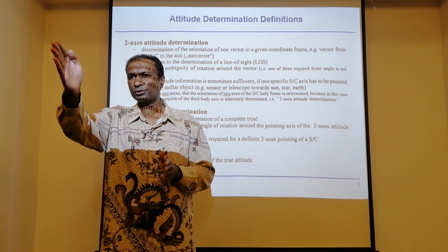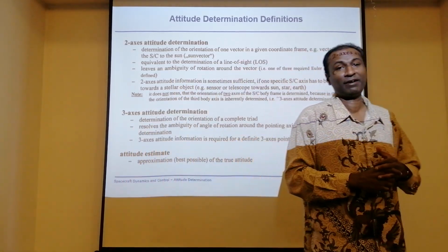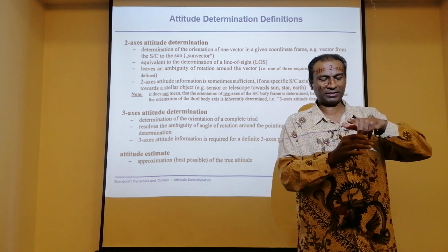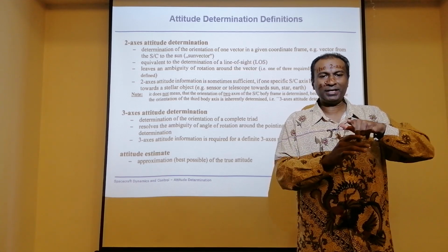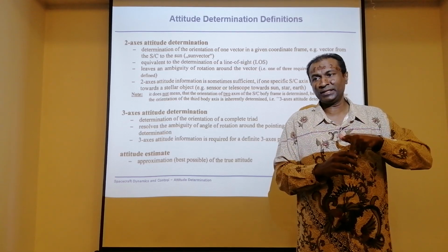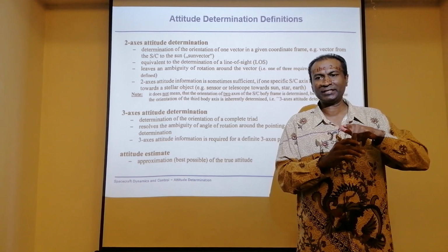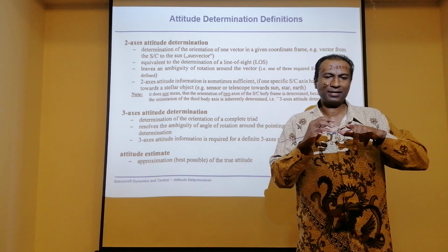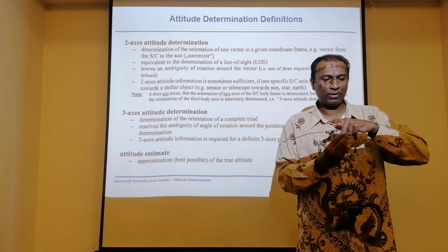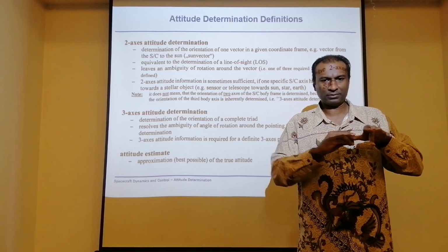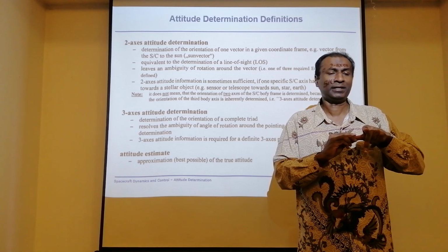Now, when your line of sight is tilted, that means the other two axes are affected. Assume this is yaw, and assume that it has been tilted. Practically, this tilting is going to affect the other two axes because they are orthogonal. So if I can sense this one axis, I should be able to tell that it has been tilted because there is some rotational motion in either or both of the other two axes. So remember, when you rotate one axis, the other two axes are going to rotate, right? That means you are inducing a particular angle.